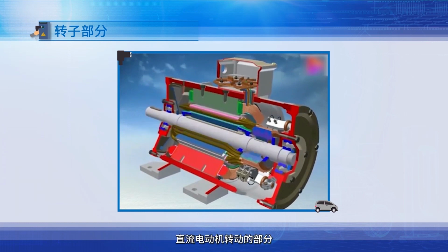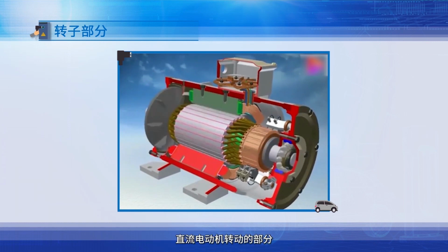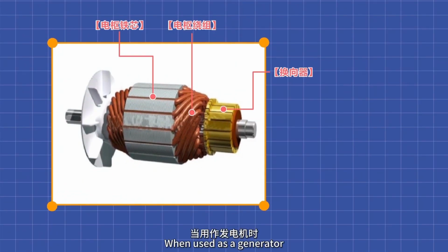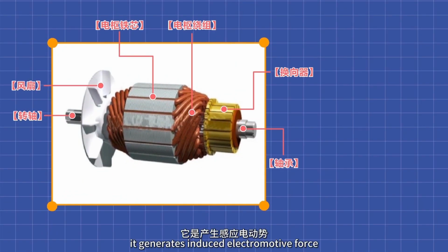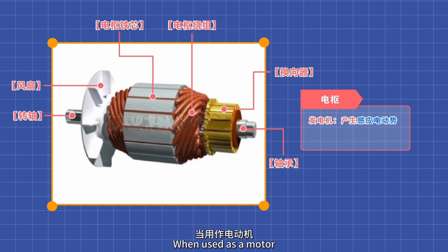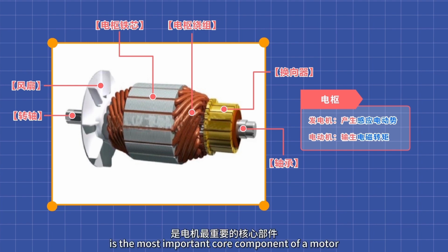The rotor is the rotating part of a DC motor, also known as the armature. When used as a generator, it generates induced electromotive force through the winding for power generation. When used as a motor, it outputs electromagnetic torque through the winding to rotate the rotor. The rotor is the most important core component of a motor.